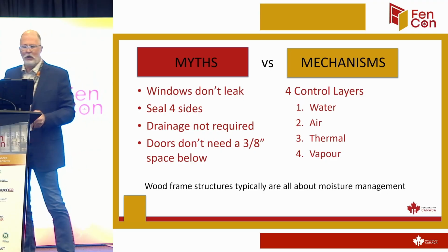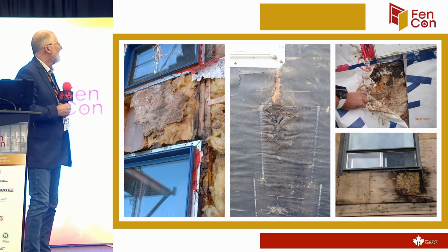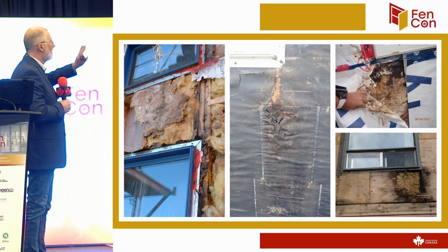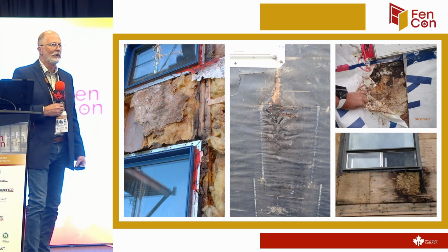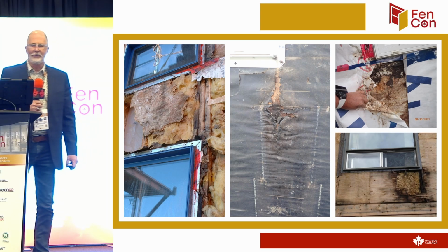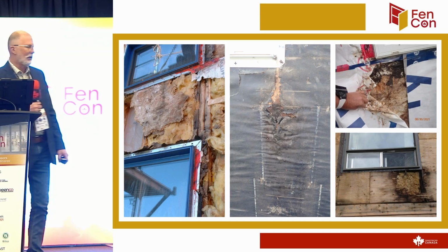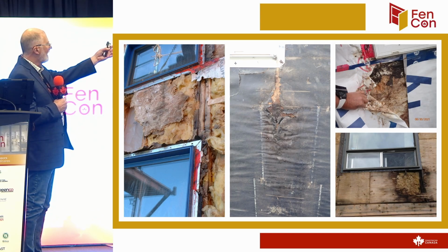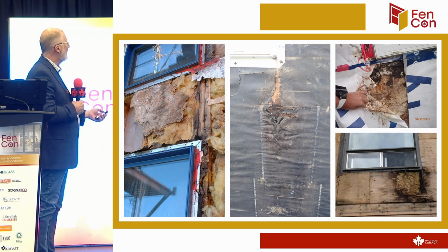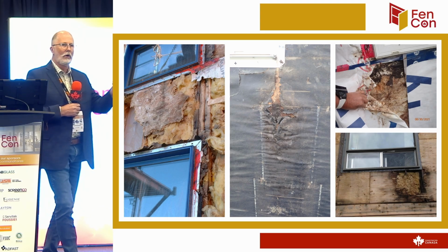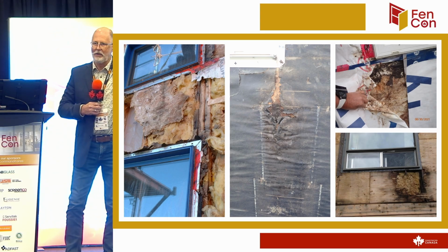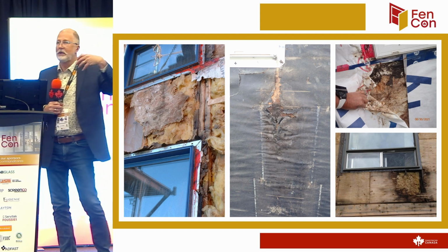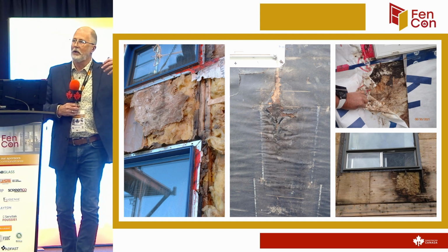So when we look at these designs and we compare what's traditional in the industry, these are some of the things that we have to be careful about. If you look at this design here, some of them have house wrap, some of them have tar paper. I have actually never seen tar paper do that, where there was enough water draining out and down the tar paper. It is an organic material, but it totally destroyed the tar paper.